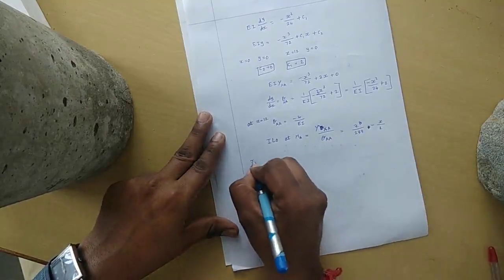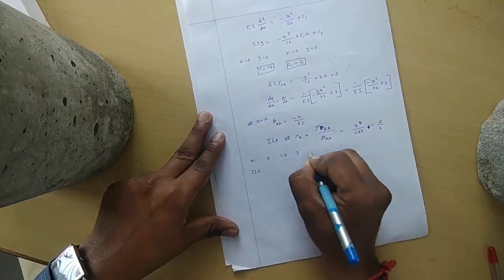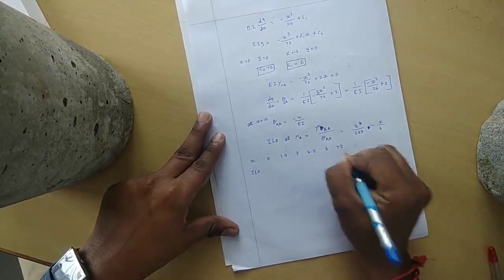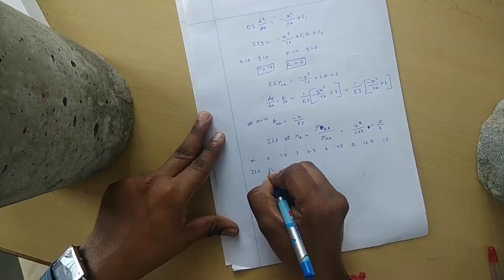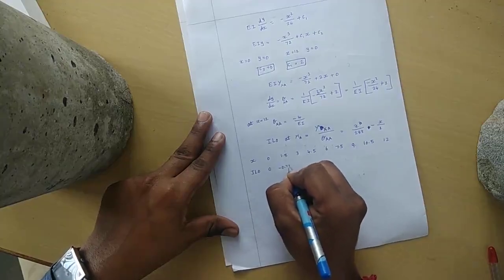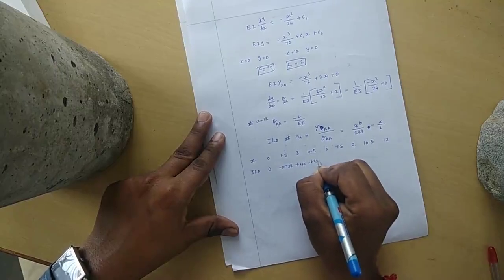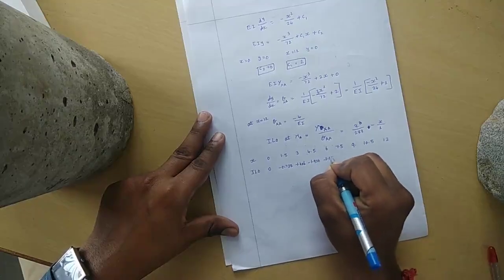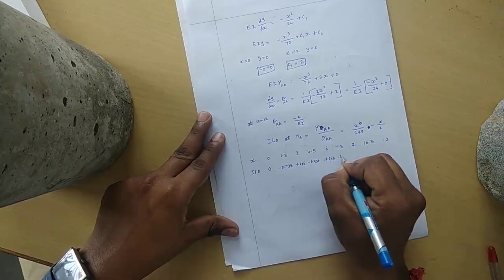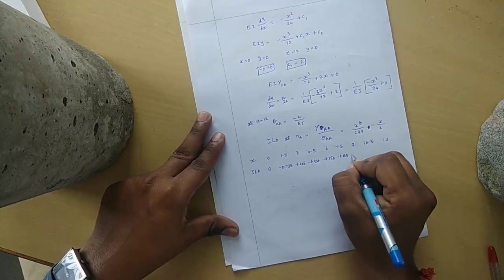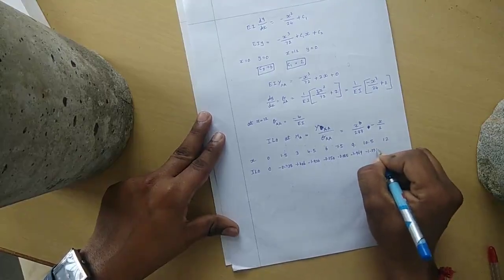Again, what we need to do is tabulate x and the influence line ordinate. So here x is 0, 1.5, 3, 4.5, 6, 7.5, 9, 10.5 and 12. If you substitute the value of 0 here, then we will get the value as 0. Then the values are minus 0.738, minus 1.406, minus 1.934, minus 2.250, minus 2.285, minus 1.969, and minus 1.230, and at the last point the value will be 0.